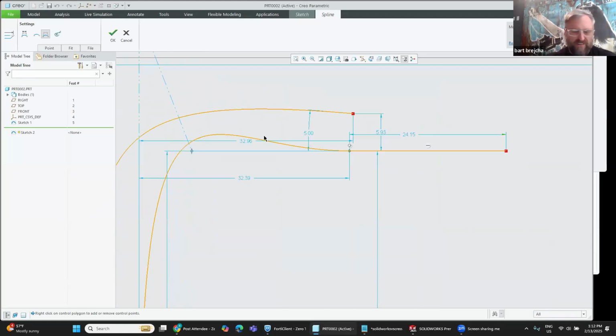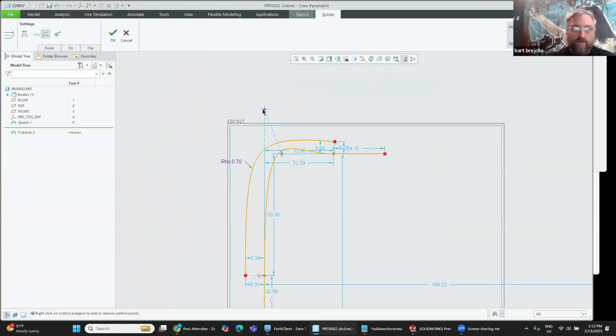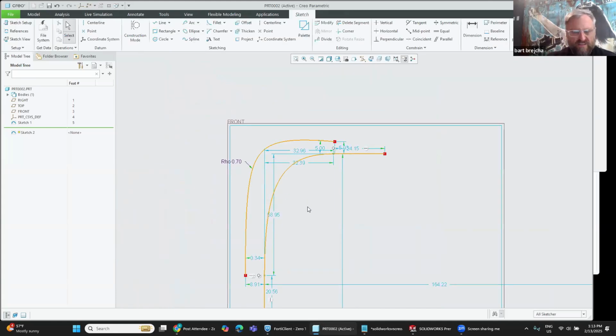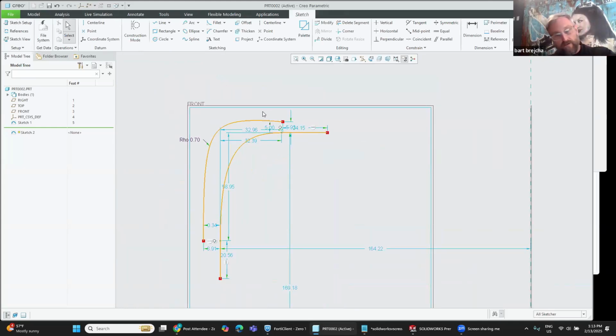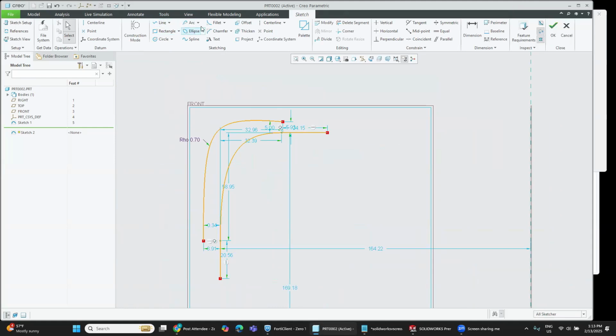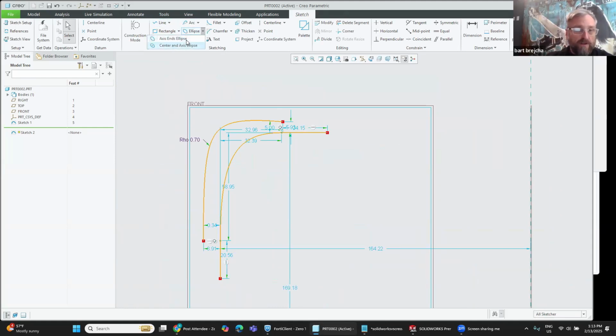MEs tend to like, when would you want to go small? Always go big. In this case, I'm getting an inflection in the geometry, which is one reason why we need a conic, because the specular highlight on that conic can always project in a certain way. So conics. I would never use an ellipse in a production model because it doesn't have the conic. Spline, I'd like to have 5 to 7-degree splines inside of Creo sketcher mode that may be coming.